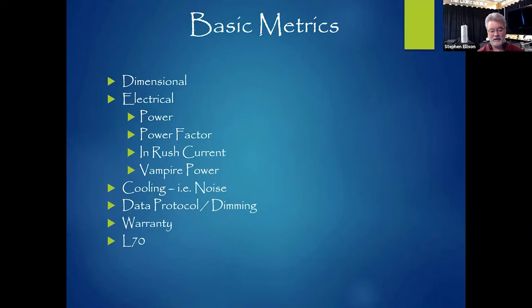Well, when I turn off the output of the light, I don't turn off all the power going to that fixture. An easy example that people don't think about too much is you have a TV. Everybody has them, and they'll have a little light down in one corner, and you see nothing on the screen. It's black, but the light's on. And if you hit the power button, the TV comes up pretty quick. That means that the electronic circuitry in that TV is always on. When you hit the power button, you're blanking the screen and taking it to a low power state. But that little light down there in the corner tells you that you are still getting power draw. So you're still consuming a certain amount of electricity.